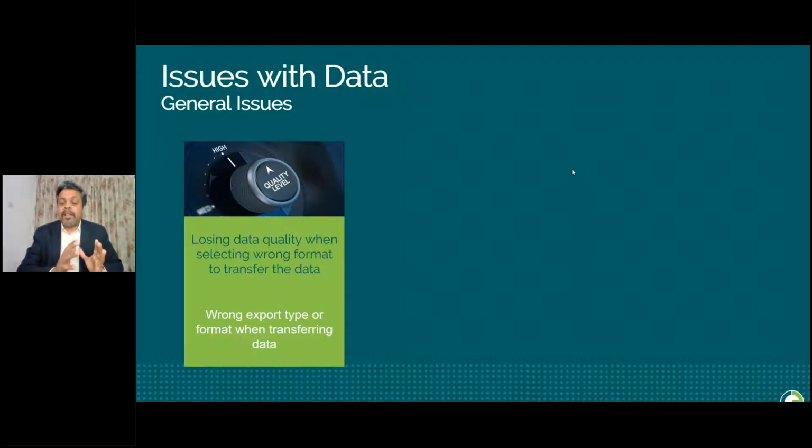There are a couple of things that we should be careful with. The data requirement for the work packaging scope. What is the best geometric object type that will give you the best rendering performance, like whether a pipe is exported as a cylinder, or as an extrusion, or a mesh, or as a faceted geometry like a bunch of triangles. This will depend on the graphic engine. So we should have an understanding on that.